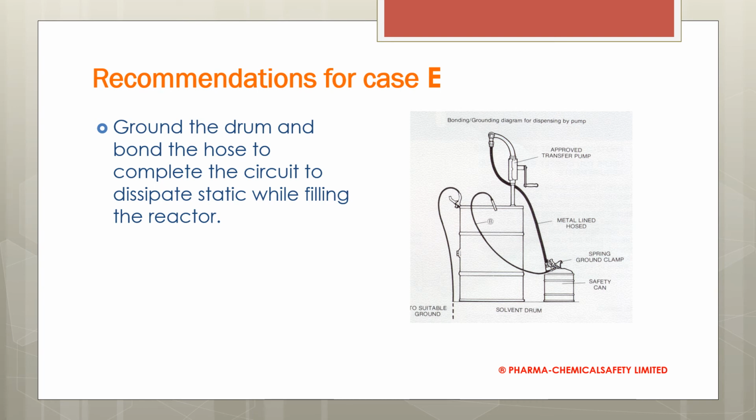Remember there is another drum, so ground the drum and bond the hose to complete the circuit to dissipate the static when filling the reactor. So for filling, put this schematic in your procedures as well. People need to be trained, by the way.